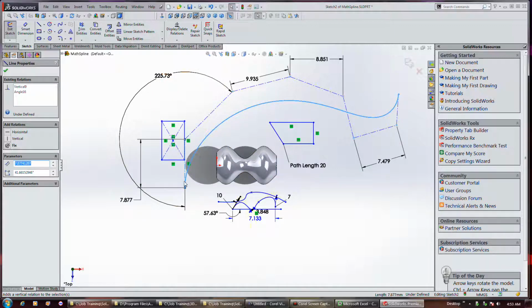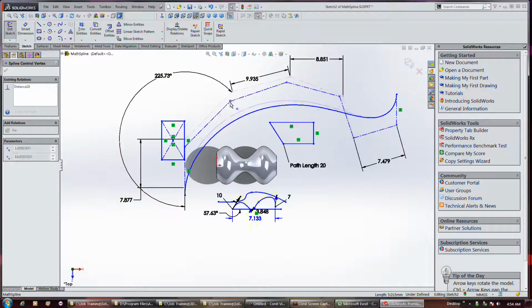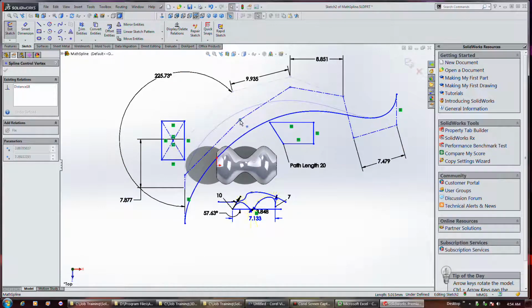But at any rate, supposedly, doing things this way gets you a better controlled curvature. So it's more fluid than dealing with a direct spline where you've got almost too much control. This tends to form better curvature, so you can put horizontal or vertical relationships, or whatever, at the endpoints, and then leave the middle available to some extent to freeform or modify within your parameters.